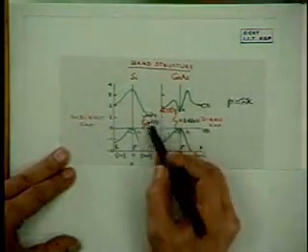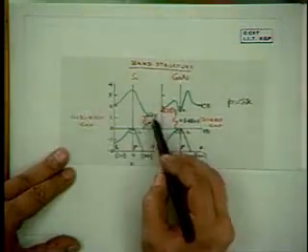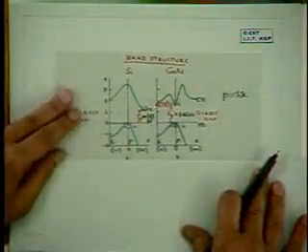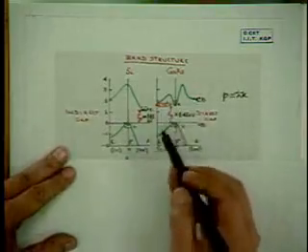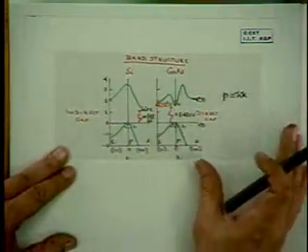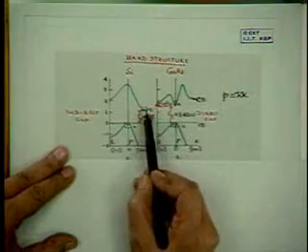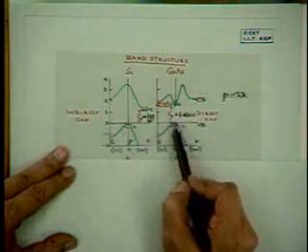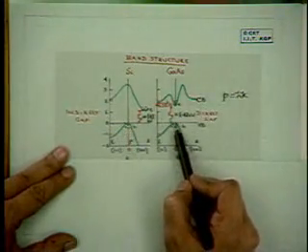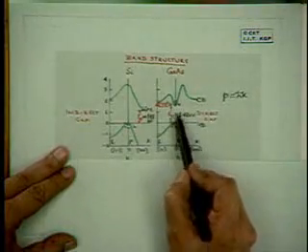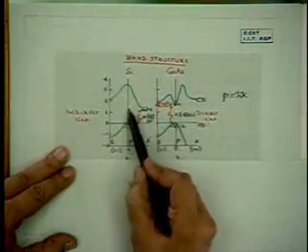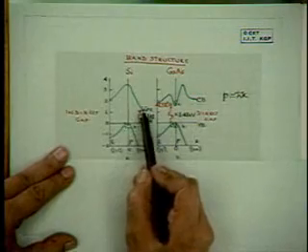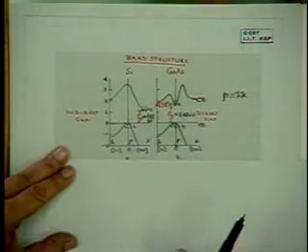However, as you know, such absorption processes involve both the conservation of energy and conservation of momentum. And notice here that the momentum of the electron is not the same as the momentum of a hole. Here, the electrons and the holes have the same value of k, so there can be conservation of momentum by a direct transition. Here, there is non-conservation of momentum by a direct transition, and some other entities, lattice vibrations, have to come into play.